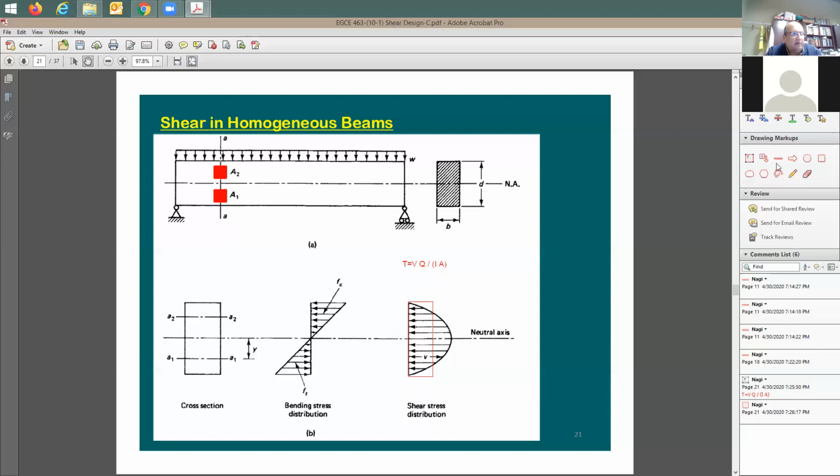So my job here, since I'm going to be taking this for A1, is to draw a section here and then figure out the amount of normal stress on the X face and the amount of shear stress, which I can take from here. So after I do the stress distribution for normal stress and shear stresses, I can figure out the amount of normal stress at stress element A1, and the same thing when it comes to the shear. I can also repeat the same thing when it comes to stress element A2.